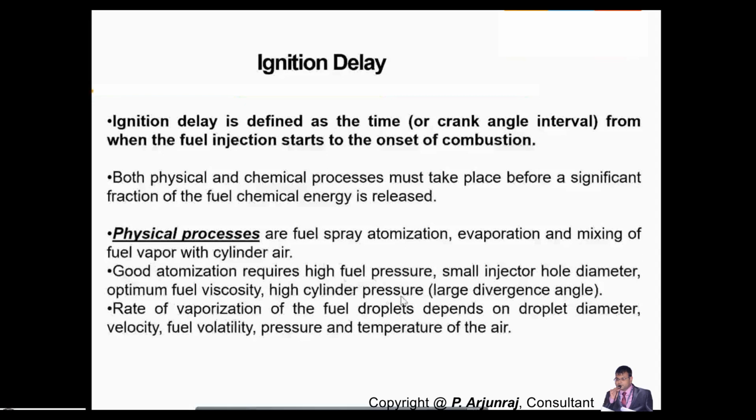Initially it started with 1,200 bar. Now they're reaching towards 1,800 bar, and many vehicles like Toyota are going up to 2,500 bar. By increasing the pressure, you're going to get good atomization as well. And here you're also going to have a small injector hole diameter, and this will also optimize the fuel viscosity, because the viscosity will also be much better.